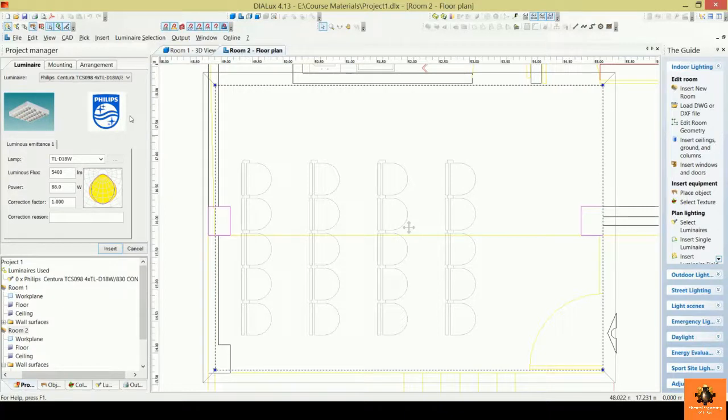So we cannot get the benefit from all of the luminaire lumens, as there is some dirt on the luminaire surface due to dust. And for that reason, we practically put the correction factor at 0.8 instead of 1. So let's change it now to 0.8. And this is to clarify that there are some losses in the output of the luminaire.